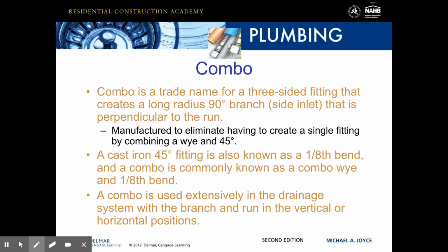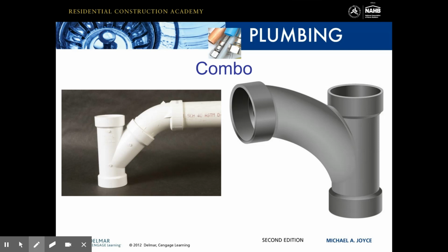A combo is used extensively in the drainage system with the branch and run in the vertical or horizontal positions. And here we have a picture of a combo. Now you can see how similar this is to a Y, except that this portion is extended out.